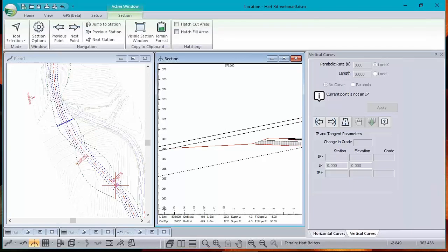New question. Boy, these are complicated questions. Good thing the answer is fairly easy. The question here is, can the template have a variable ditch bottom so that the back slope will hit the right-of-way at a constant slope? I think that's the idea. Yeah, we've made ditches to do that exact thing.